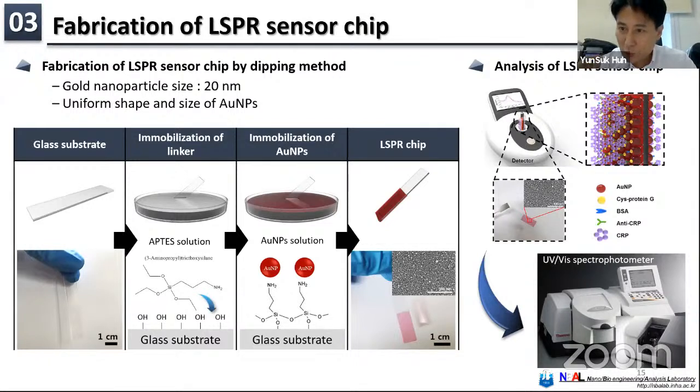That's why we choose transparent substrates such as plastic and glass substrates, and via surface treatment with APTES, using the amine functional groups, we can densely pack the gold particles onto the transparent substrates. You can look at it; we can verify how the gold particles are packed onto the substrate.